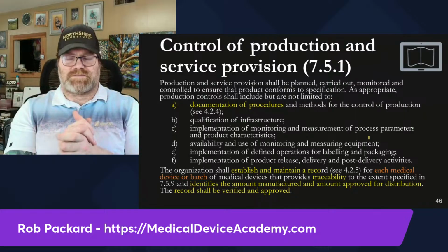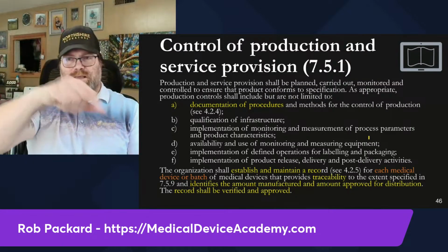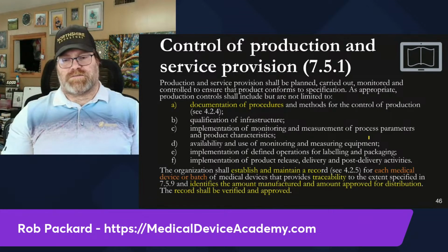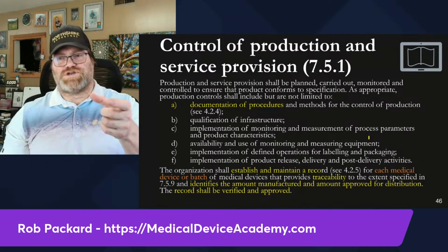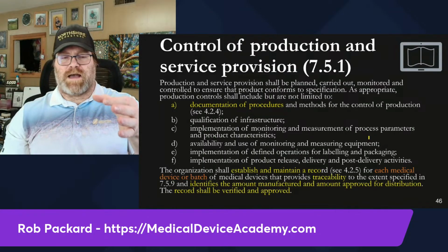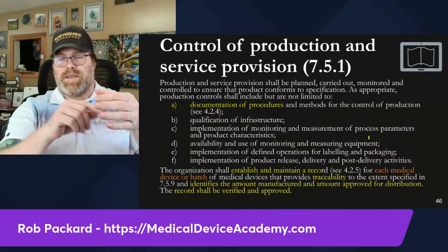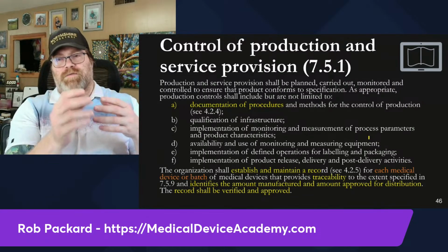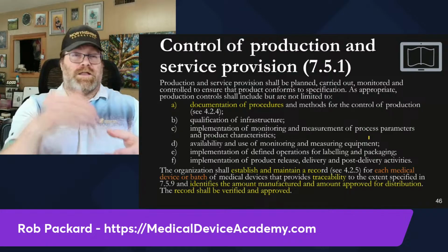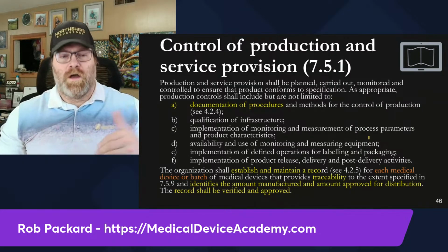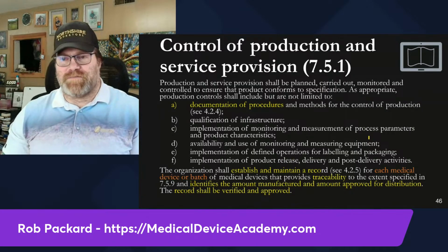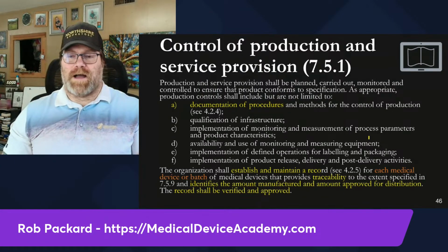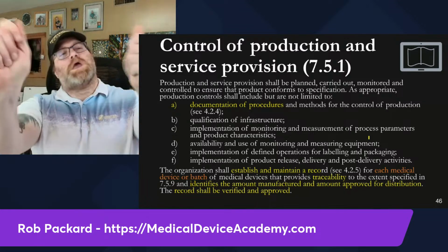Then they have continuity tests, ICT testing, like a bed of nails coming down and making sure that there are no shorts in the board. And then they have functional tests in these boards. And then they have X-ray. If you have a BGA style IC, that chip has little beads of solder underneath it, and you want to make sure that there's no shorts there where you can't see, and you can only see by X-ray. So these are all the methods they use in addition to visual inspection. And it's all automated. So much, much higher confidence level than it looks good.